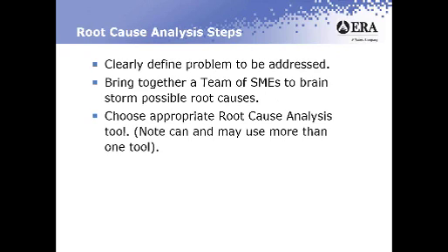The other piece is you don't want to do your root cause analysis in a vacuum. You want to make sure you have the right subject matter experts available. I also like to have somebody that's maybe not closely tied to the problem or the issue, because they can bring an outside or a different perspective and ask questions. And then you want to choose the appropriate root cause analysis tool. In some cases, the 5Y may be better. Other times, it might be the 5W1H. It could also be the Fishbone or the 4M methodology. And many times, you may end up using multiple tools to get to those root causes.